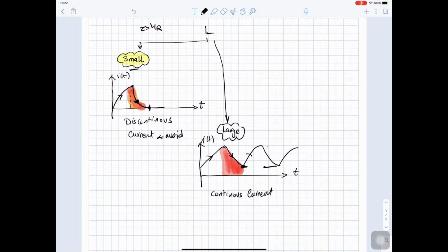The difference between these two peaks: we call this current I minimum and we call this current I max, and the difference is delta I, and delta I is called current ripple. And you can see in some design requirements or design specifications that they put limits on delta I, they put limits on the current ripple, so you are not allowed to exceed this current ripple.